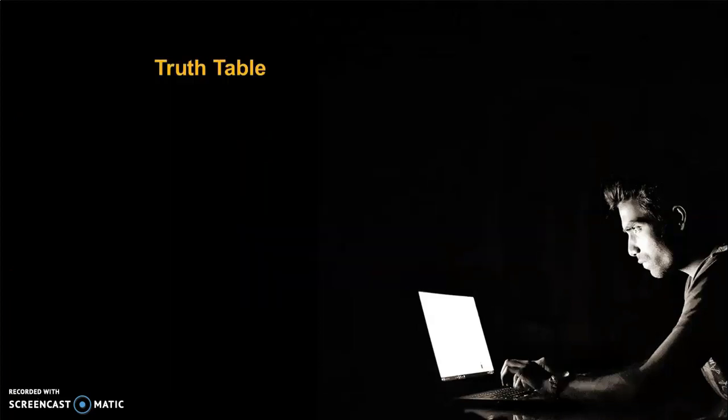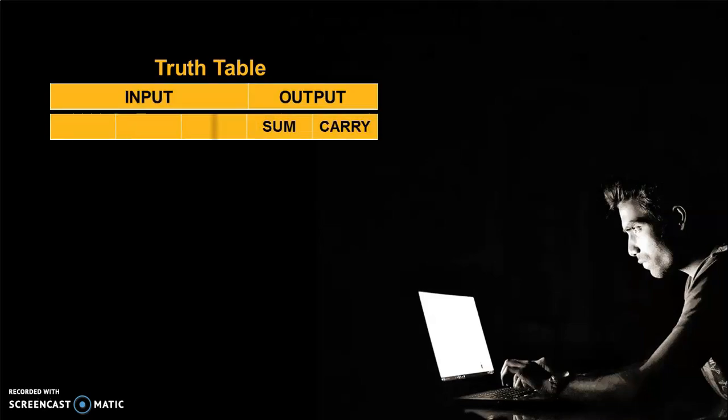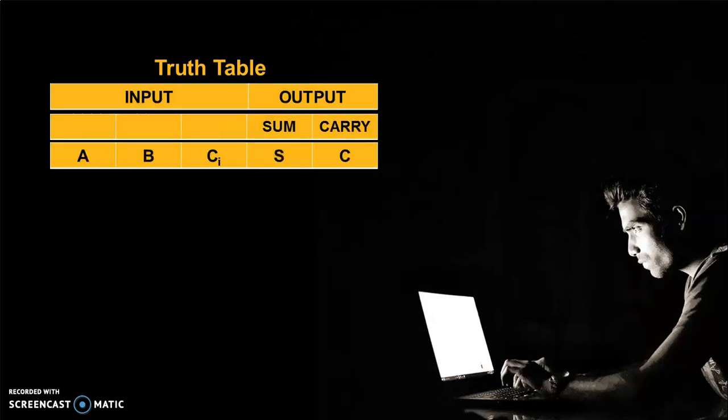Now let us understand the truth table for the full adder. We have inputs as well as outputs. In case of input, we have three inputs: A, B and carry Ci. That carry is from the previous stage. And at the output side, we have final sum and final carry.